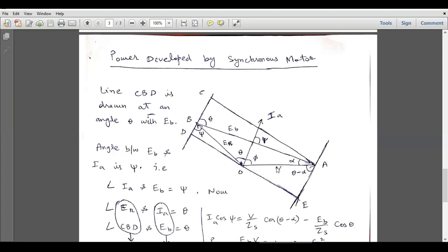So this is the applied voltage vector starting from point O to point A. The back EMF vector is starting from point B to point A, and this is EB dash. This is the convention which we have used from the previous discussion, and the vector from point O up to point B, or the vector from the tail of the applied voltage vector to the tail of the back EMF vector, is the reactance voltage vector ER, and this is the orientation of the armature current vector.